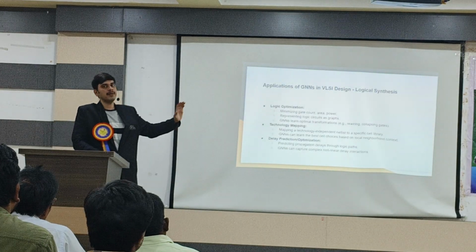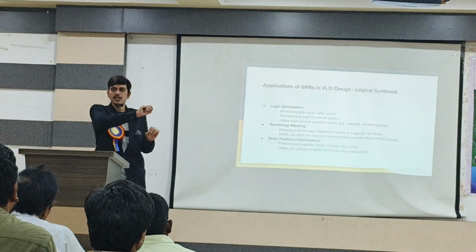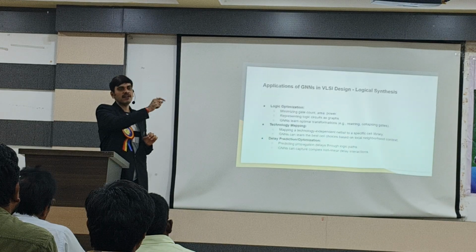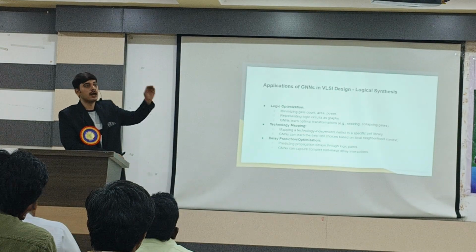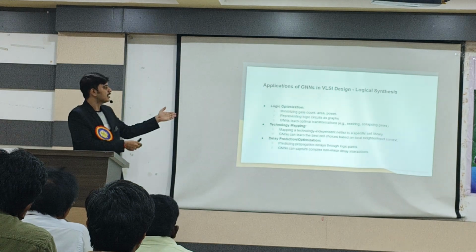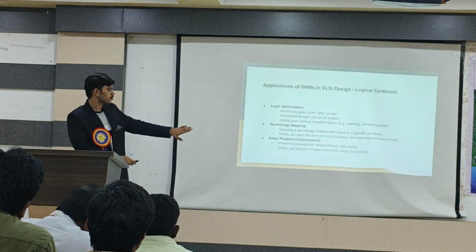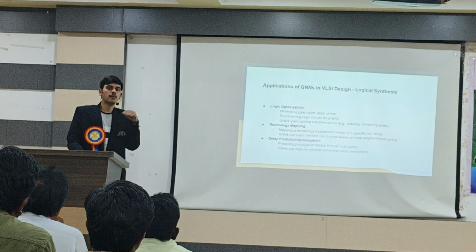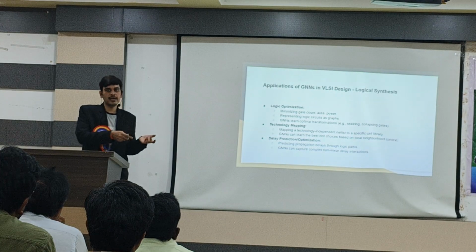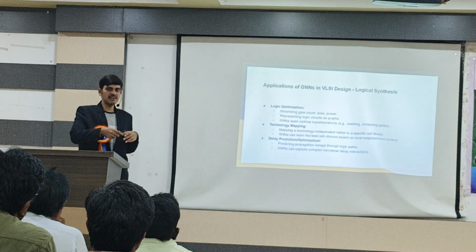But in the normal initial mapping, the initial instance is an AND gate, for example in RTL logic, just an AND gate. Once the AND gate is there, it is mapped as a technology map. Based on that, for example, a 4 input AND gate has more area and more delay than a 2 input NAND. So the delay calculation and everything gets done there.